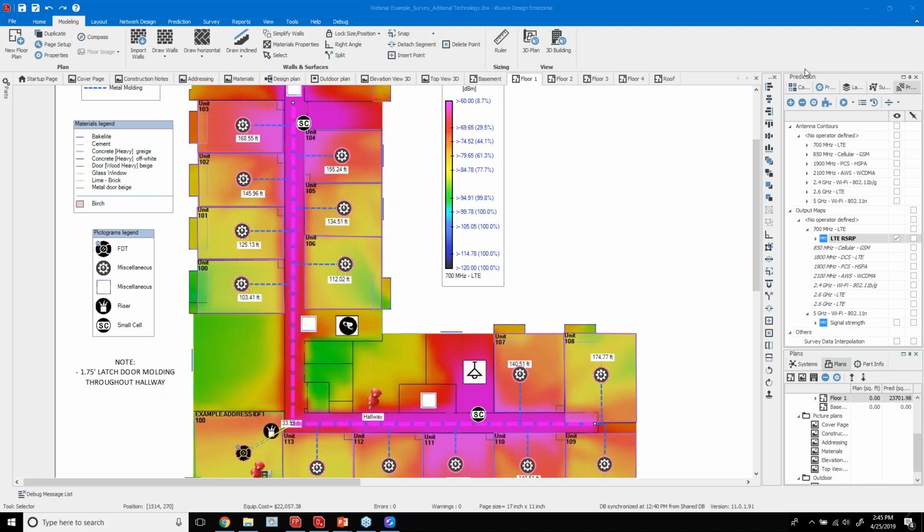So it's certainly worth evaluating what technology do you want to deploy. If you're going to deploy an Ethernet solution, maybe you want to run two multi-mode fibers to each unit. But if you're servicing a larger area, if you're a small operator and you want to invest in GPON technology, then you're going to have to leverage single mode fiber. Okay, great. Thank you.